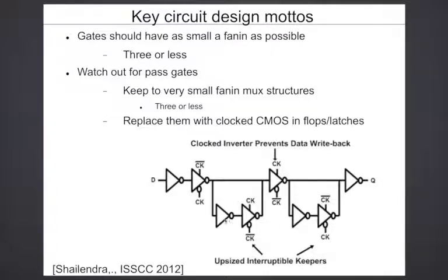And what is a latch? A latch is basically two back-to-back inverters. Then there is a mux. In a standard super threshold latch, there would have been a transmission gate here and here, and then you would have either a tri-state inverter or another transmission gate. So what these people do is they remove this; instead of putting a transmission gate here, they use a tri-state inverter.